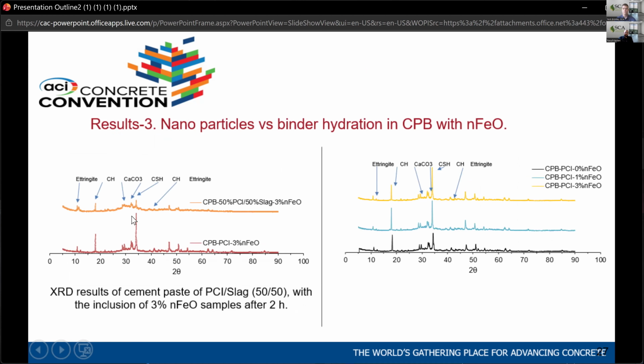These are the results. You see, the intensified result means more hydration, since more materials are produced with more hydration. The XRD shows you the materials within your sample. So the more material resulting from hydration we have, the more hydration we have, obviously.